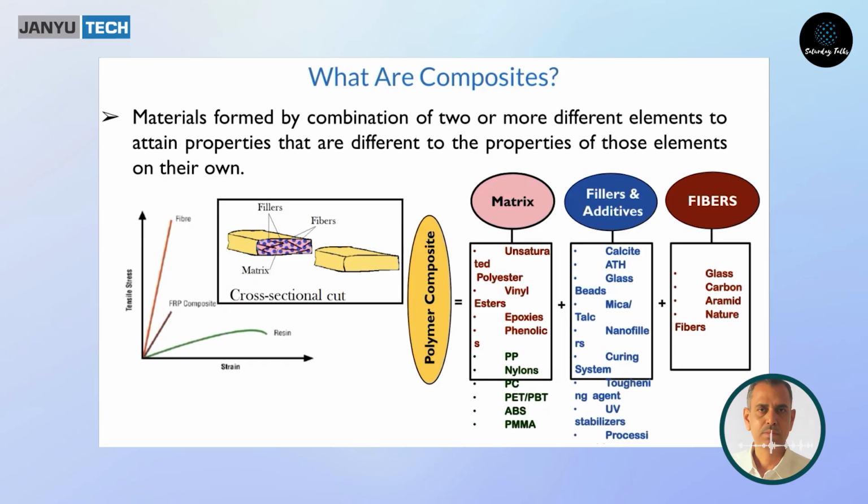If you look at the strain axis, from here we can define the strain percentage of resin, because the first thing to happen will be the resin failure, the crack. So we can design that way. That is why we call composites tailor-made and engineered: materials engineered and tailor-made for meeting a specific end-use purpose.